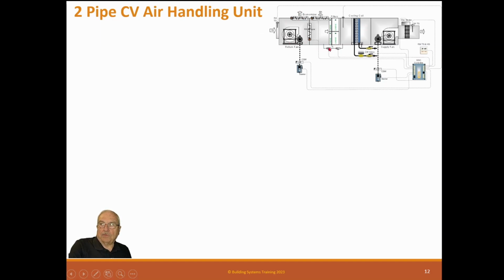These happen to be filter switches. Now, this is the only unit I've shown filter switches on, even though they will be on most units. And the reason is filter switches don't work that well. On a constant volume, they can work, but they're not well maintained. They don't usually work very well. The correct way to do filters is to have experience in the building and decide that the filters need to be changed at a certain interval.